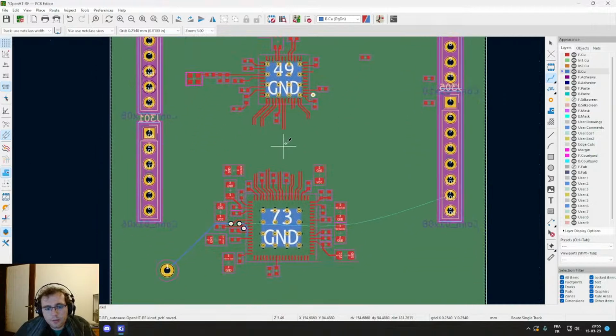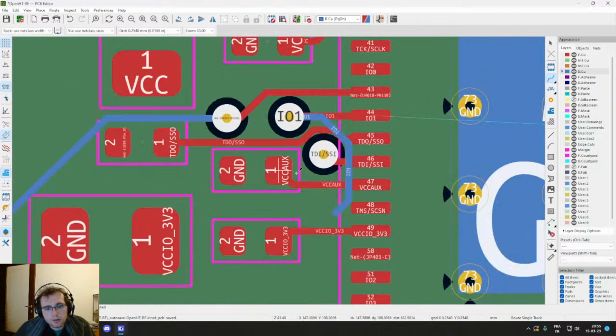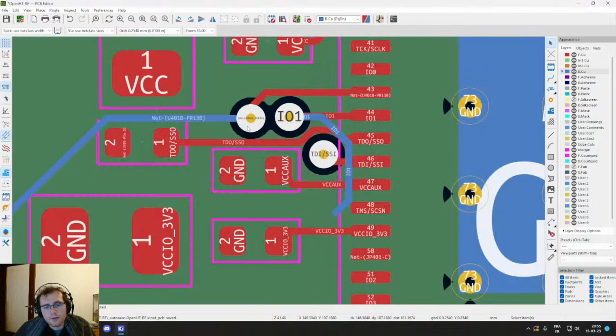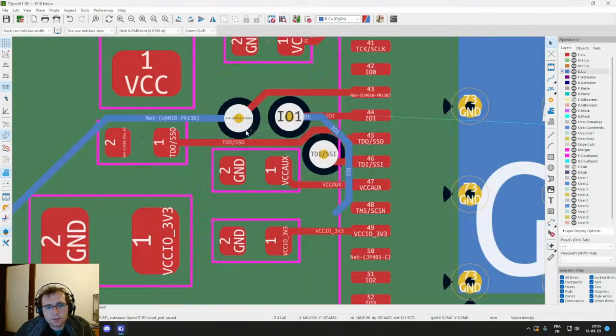But it's recommended to pay attention not to put vias too close from one another to keep from having large openings in the plane. So what we usually do is keep things like this, so that there is a small sliver of copper between the vias. If we put them too close from one another, then we have one bigger opening, and it's not the best. We try to avoid that. So like this is good.